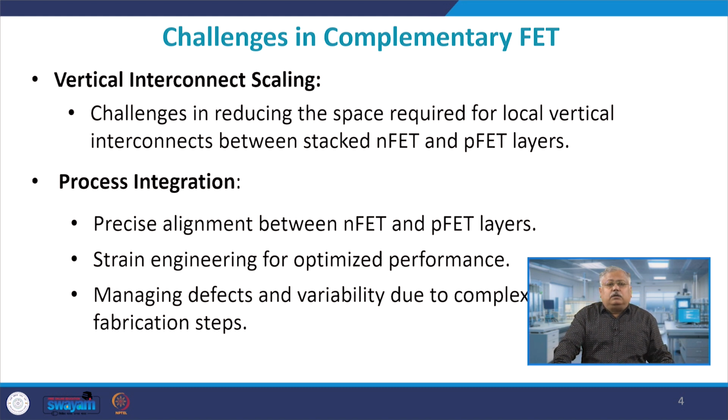Now, this alignment can be done in multiple ways, both physically as well as using characterization tools. But if, say for example, there is some misalignment, the interconnects will not be matching properly between the NFET and PFET layers, and there might be discontinuity in the interconnect layer, which might result in actually a loss of current or a reduction in the current.